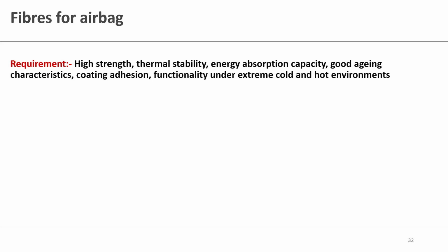The fibers required for airbags need high strength, high thermal stability, and should absorb impact energy. They should have good ageing characteristics, because in a car it will remain for a long time. The coating adhesion should be good, with functionality under extreme cold and extreme hot environments. So, these are the basic requirements.